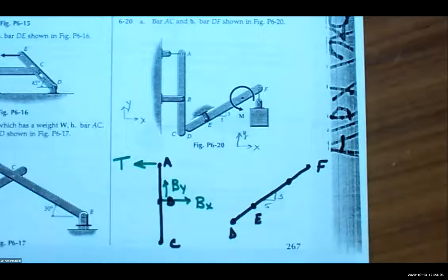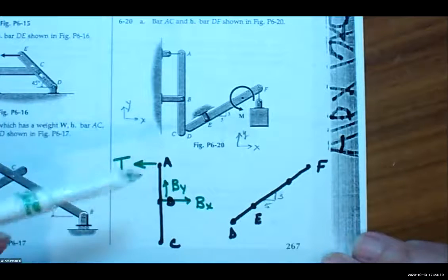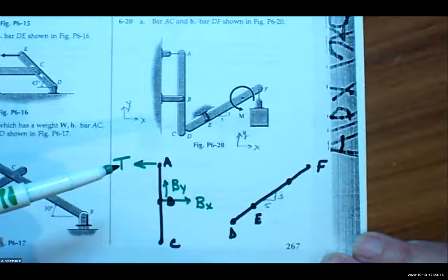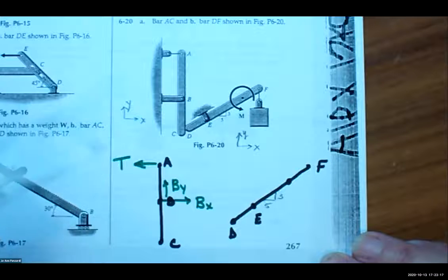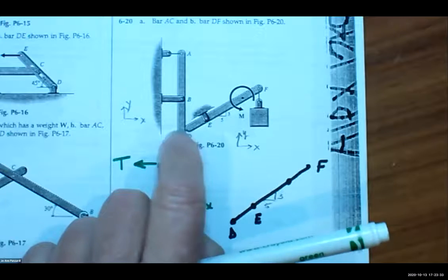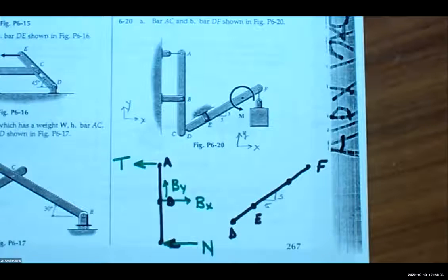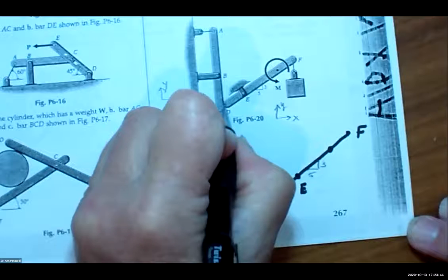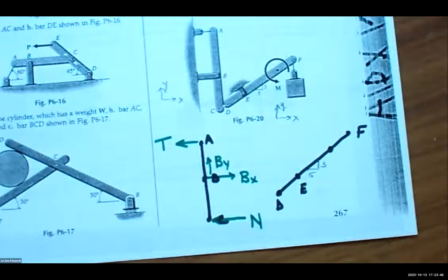And again, notice I'm always drawing them in positive. Okay, what's happening at C, Isaac? At C, a normal. We could call it force from D. Nope, we're calling it normal. I don't want to put any F's in here because I'm going to have to do some of the forces in the F later. It's a normal between C and D. Is it a normal how you drew it, at that angle? It's touching right here. It's horizontal. Because she said assume everything's smooth, then it would be. If there was friction, there would be a downforce. But we have no friction yet.